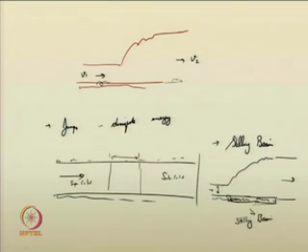Why is it called a stilling basin? Because the bed of this stilling basin is designed with proper aprons and paved materials, such that erosion or scouring is prevented in those locations, and it can also sustain the high pressure created by the hydraulic jumps.